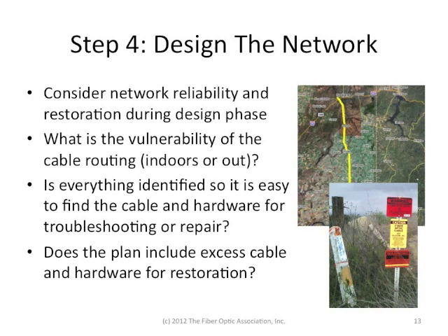The reason we said that you should physically walk or drive the route of the cable plant is it gives you an idea of what network reliability and restoration issues may be. What's the vulnerability of the cable routing, both indoors and out? Where is it likely to be damaged in the future, and how easy will it be to troubleshoot and repair?